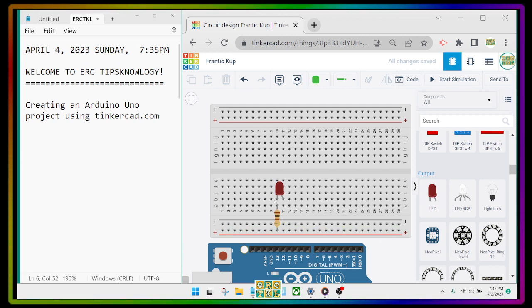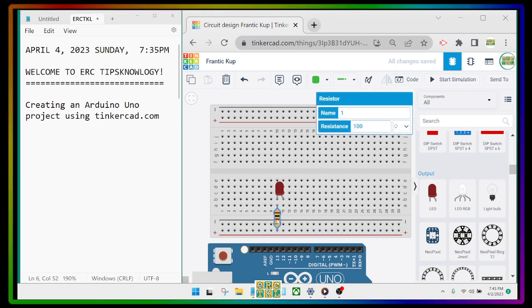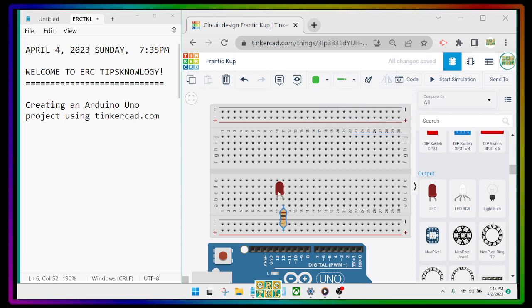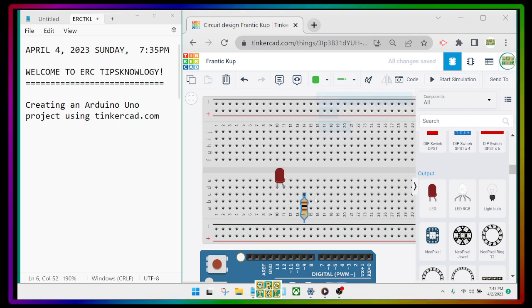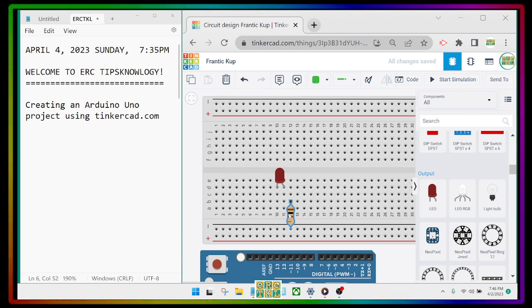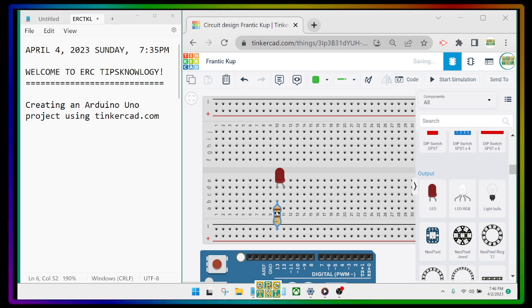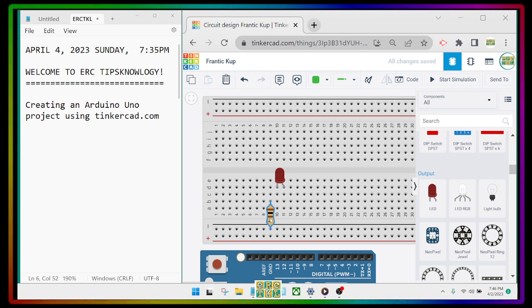All right, now if I connected my resistor on the positive, or maybe it's better if we connect it on the negative. So what I'll do is I'll bring up the LED on D10 and D11, and then my resistor will be on B11 for terminal 1, and my terminal 2 will be on the negative. Or you can also use B10 for your cathode. Okay, so the cathode is connected on D10 and my resistor is connected on B10 and then connected to the negative.